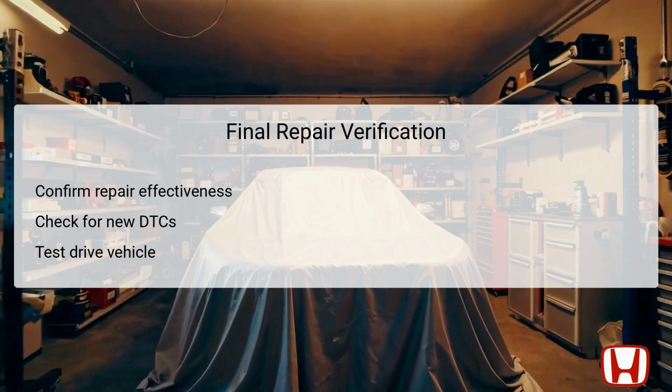After completing the necessary repairs for DTC P0970, it's critical to perform a final verification to ensure that the issues have been effectively resolved. Start by rechecking the vehicle using the HDS to confirm that no new diagnostic trouble codes appear following the repair. This process not only validates the initial work, but also ensures that other components of the system remain functional. A test drive of the vehicle is also recommended to assess overall performance under various driving conditions.